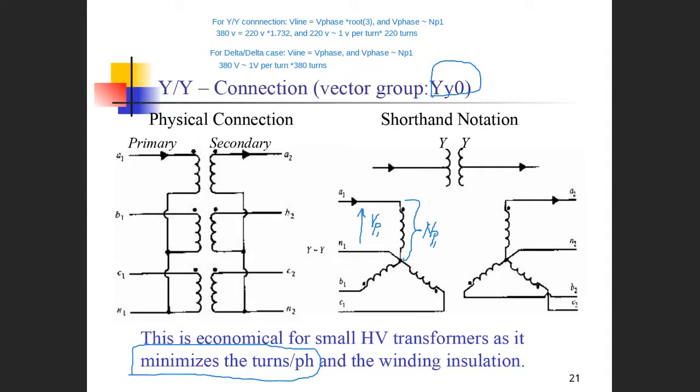Okay, so I think you have understood these problems. That's the meaning of it. Because in star connection, per phase just needs to produce 220 volts if the line voltage is 380. But in the delta connection, the per phase should produce 380 volts if the line voltage is 380. These are examples, but you can get the same for other line voltages.